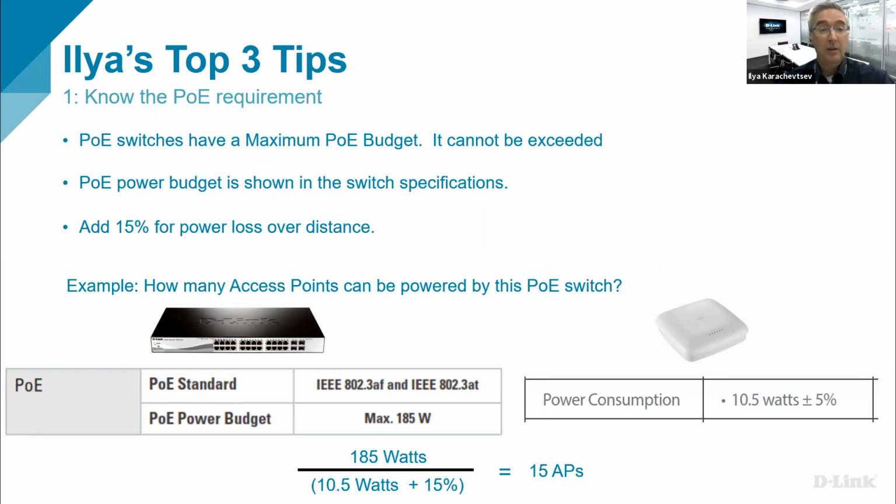So even though the switch can be, say, a 24-port PoE switch, if your devices are power hungry, do not expect the switch to be capable of powering all of them, or you would need a switch with an extended PoE budget.